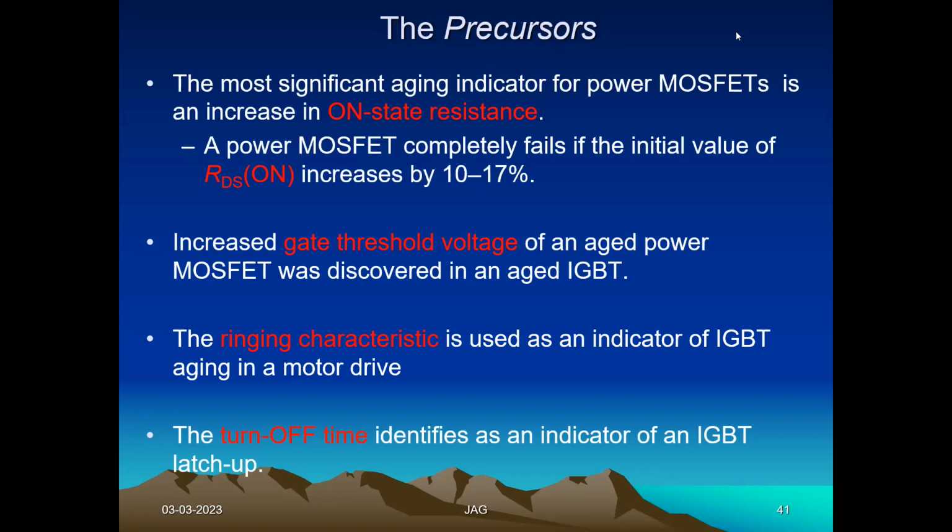So monitor the output voltage of the inverter, continuously check whether every part of the voltage is available. If there is a change, you can either send an SMS to the user or the technician who can repair it, or the OEM cloud. All these are happening using IoT. Development in that IoT system also can be a challenging research area, right? And then the technician can attend the problem in time so that an unexpected failure is totally avoided.